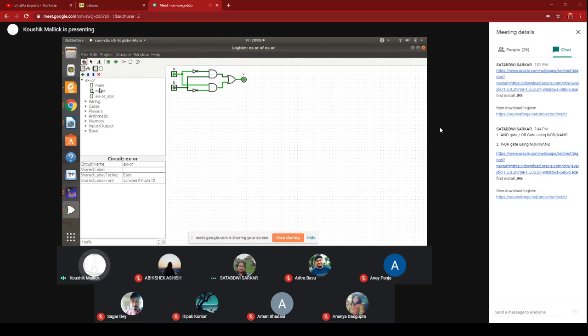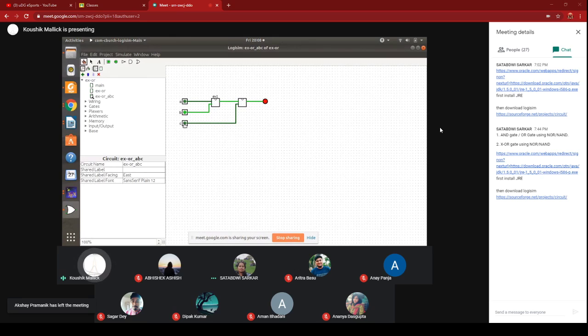Save will give a name of the circuit. Then you click on XOR. This is your project. So add circuit. To do a new circuit of XOR ABC, you edit the circuit and use the previously done circuit, and then it will do a XOR ABC. So you can try it on your own using a little bit of variation, you will get the result basically, right?